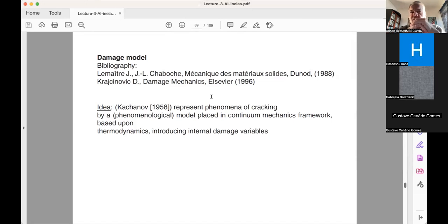Honestly, I never really understood the predictability of such a theory, because the problem is that typically a finite element computation would not give you an exact result. Even in a 1D setting, unless it's a special case, you don't get an exact result. In 2D, 3D, it's practically impossible. So if you're not able to get an exact result for the elastic response, to get displacement, strain, and stress correctly, there's no way you can really predict the crack. Putting a crack on top of the finite element mesh looks appealing, but in fact, the predictability is tough.